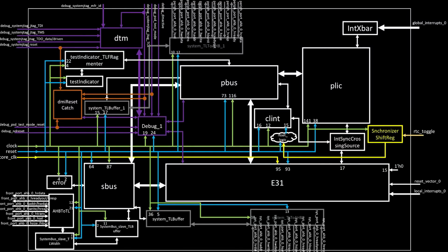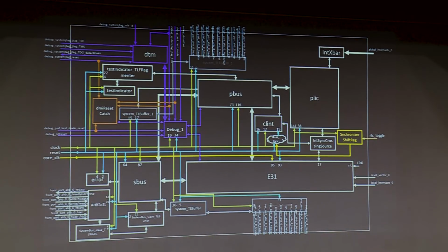You should see a picture like this, and as expected, if you provide this kind of information to any EDA tool, be it commercial or open source, then in almost 90% of the cases your top level chip layout will look something like this. If you place the pins over here, and place all these blocks at these respective positions, more or less your top level floor plan will look something like this, and that's what we expect. We expect the latency to be optimum, and we expect the area to be optimum for this arrangement of the blocks and the physical location of the blocks.